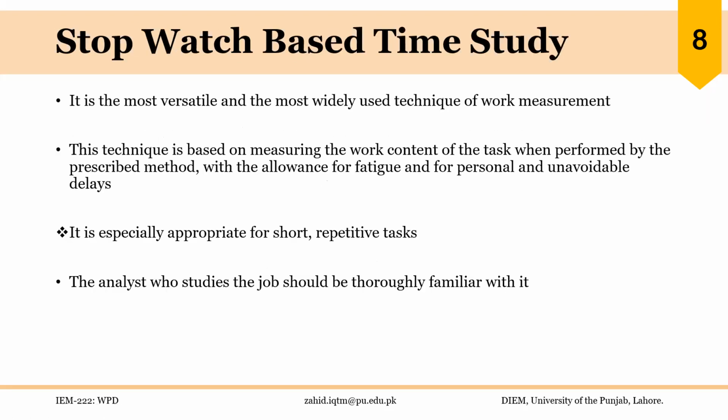So stopwatch-based time study is the most versatile and the most widely used technique for work measurement. This technique is based on measuring the work content of the task when performed by the prescribed method, with the allowance for fatigue and for personal and unavoidable delays. This point is very important, that before actually finding the standard time, the task must be standardized.